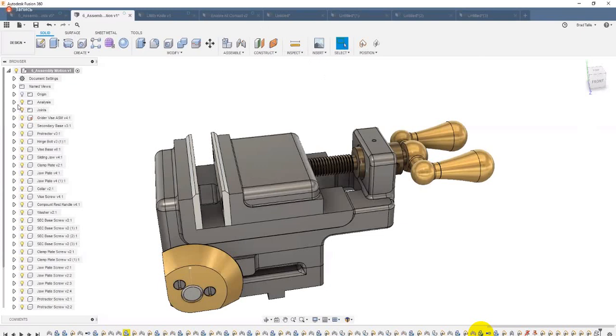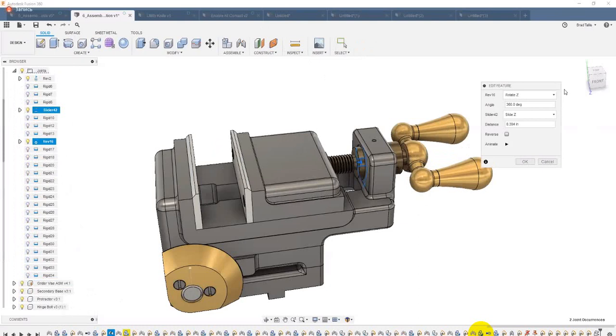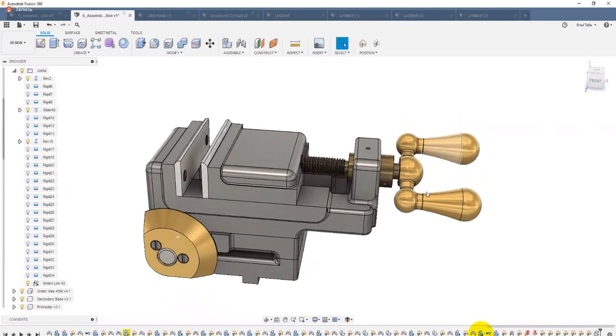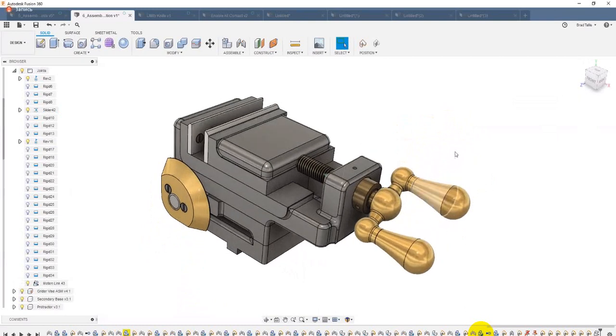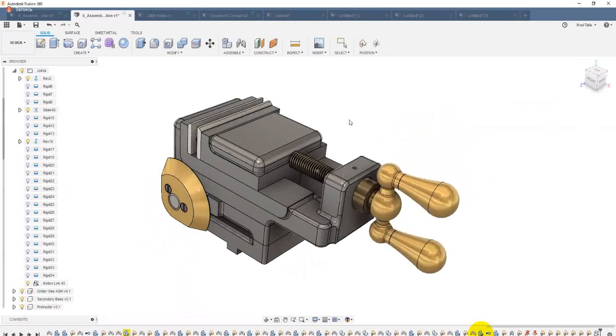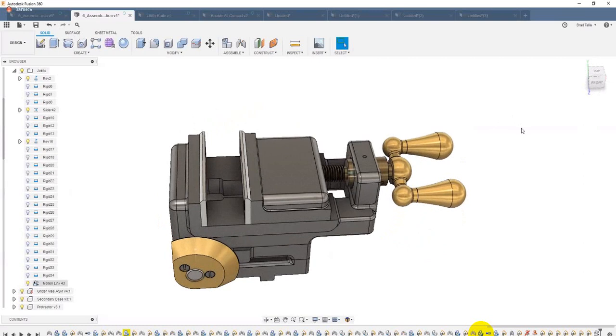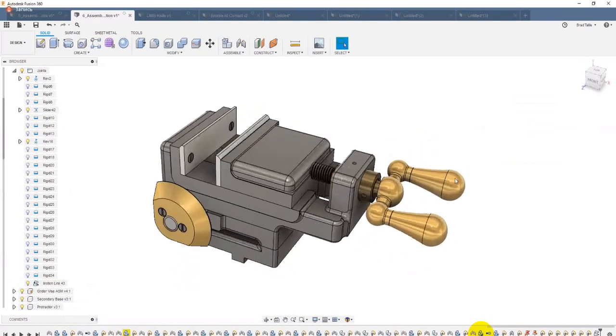So this is a really good way to simulate, for example, if you had a small gear and a large gear, you'd have two revolute joints and you would motion link them together and you would say for every revolution that the small gear goes, the large gear only goes a quarter of that, for example. Now what's neat is I can come in and I can edit that. Let me just edit this motion link. And we were saying for every 360 degrees, go about 0.4 inches. Let's go about 0.04 inches. So now watch, as I crank, you're going to see it barely slide. So I'm having to crank this many, many times to get the slider to go, okay? So you do have control over that ratio, okay? So I'm going to put that back. And you can reverse the direction in case the gears are turning the wrong way or whatever, you can do that. But now we're back. Okay.